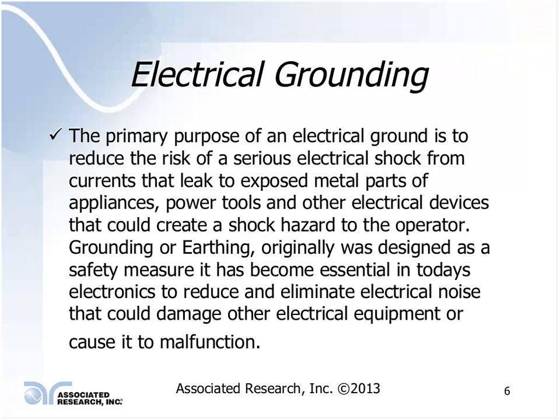The primary purpose of an electrical ground is to reduce the risk of any serious electrical shock from currents that leak to any exposed parts of the appliance, power tool, or other electrical conductors that could create a shock hazard to the operator. It may not necessarily be a short circuit.